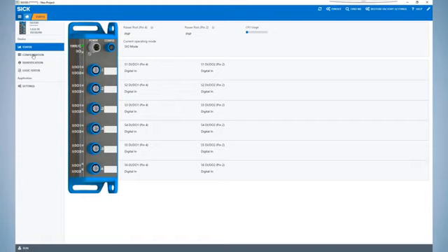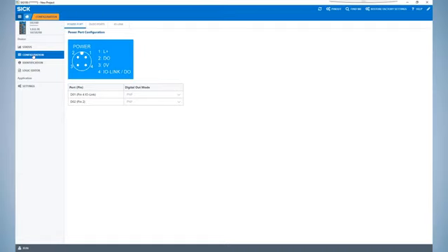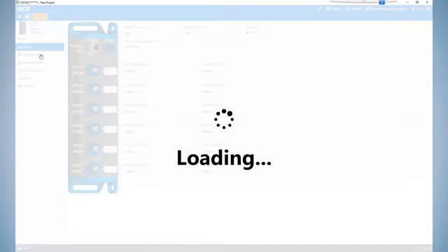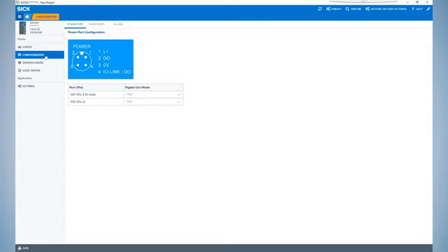Note that the button is highlighted in light blue when the device tree is hidden. The home button will always navigate back to the status configuration page. The status page is the home page and shows the input or output state of the connected SIG 100 along with the port configurations. The configuration page allows configuration of each M12 port on the SIG 100.